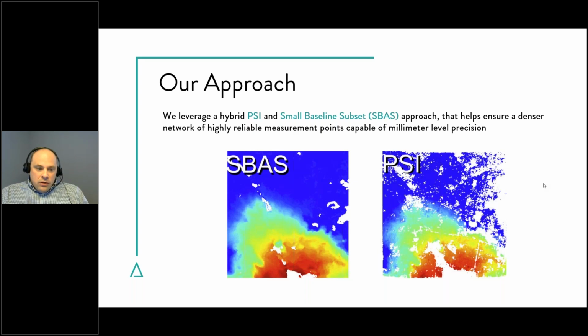Here, what we're doing is allowing all combinations, so we can combine the richness of observation of the SBAS approach and be more stringent on what goes into a stack with the persistent scatterers workflow, as Sean said, that can extract lots of reliable points. So we're working only with points on which we have confidence, and all the low coherence areas are wiped out from the process. Next slide.